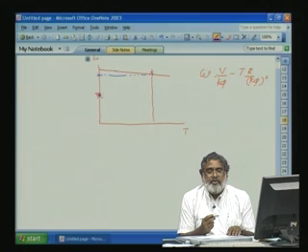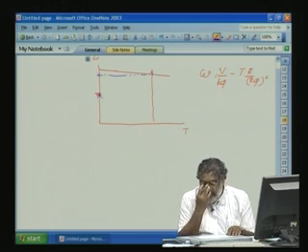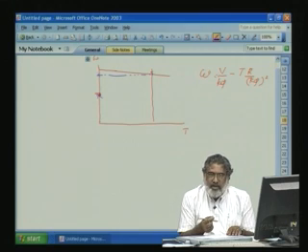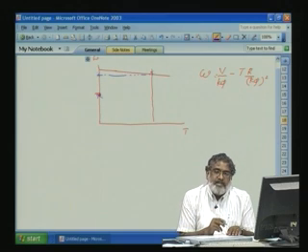Now, current will come to 0, and when the applied voltage is equal to EB, again we slightly reduce the voltage, and EB will supply current back to the source, assuming the source is capable of taking this. Now, we will again slowly reduce the voltage, so that we draw the maximum current from the machine, such that the maximum negative torque is applied. So, with the maximum negative torque, the system will be able to decelerate very fast.